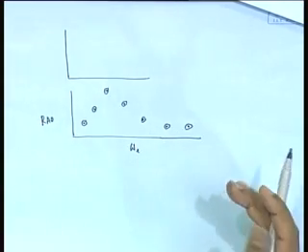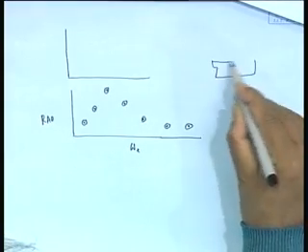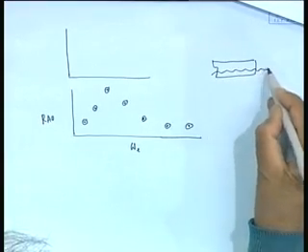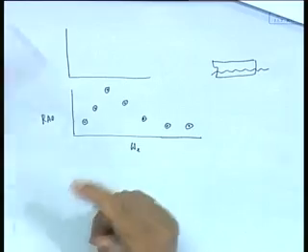Normally what happens, you would like to calculate this, but as I said, this is the most cumbersome part, over a range where the ship responds fairly well. If you take waves which are very small, if you ever go to a port, you will see small ripples, and the ship does not even move up and down at all. So if the wavelength is much smaller than the ship length, maybe 1/4 or so, there is typically no response at all. If you go to a very long wave, you will find that it simply goes up and down with the long wave. We have actually done that; it goes to 1 for heave motion.